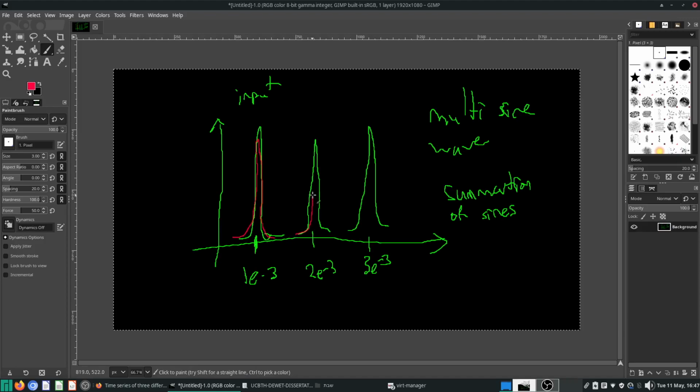So if you have two frequencies now, maybe you have this curve here. Maybe you have some non-linearities here as well. But if your noise is negligible, we can just take the ratio of these peaks to be our gain, and then of course we can look at the phase as well. This is a very good method if your system is indeed linear time invariant.